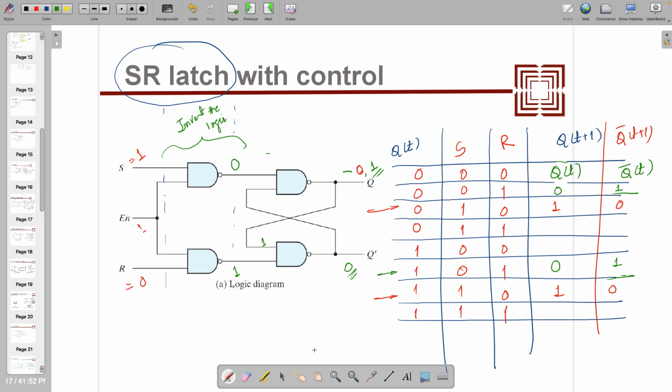So whenever this enable is 1, then and then this will work. If it is 0, then it's latching. So depending on the level of enable, this whole system is working, not the transition going from 1 to 0 or 0 to 1, it's working, right? So that's why this is known as the latch, because it's working on the level of the input or the enable, right? Here you can replace that with 1 and 0.